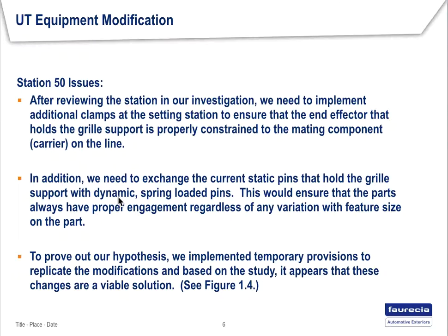In addition, we need to exchange the current static pins that hold the grill support with dynamic spring-loaded pins. So right now we have the static pins, which do engage the hole, but the problem is the hole size varies. So if we go with the tapered spring-loaded pins, regardless of the feature size, the pin will always engage the hole all the way around the circumference, which would give us better engagement and better location strategy.